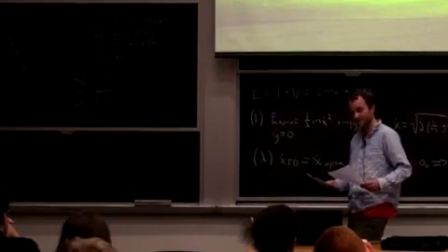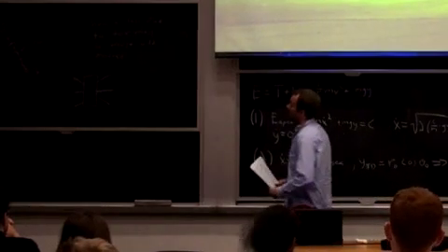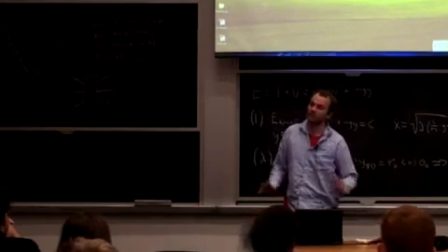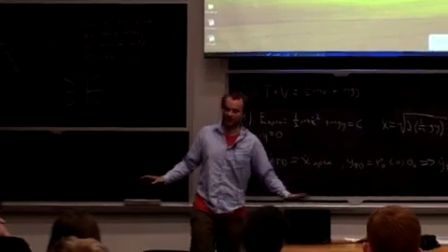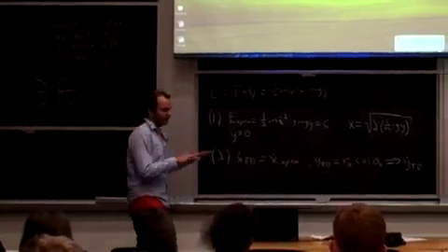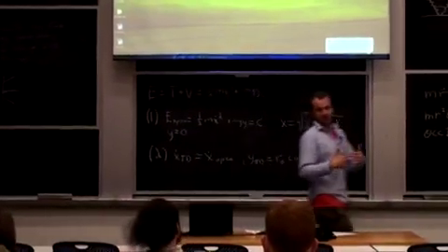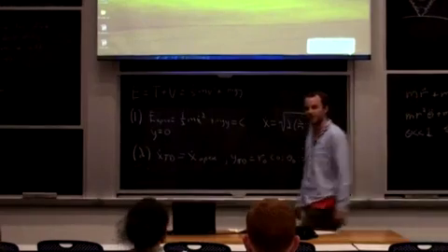In that model, is the spring actually in 3 dimensions? Is it now that you have X, Y, Z? And it's at an angle in both pitch and yaw? Yeah, I mean, if you're doing the lateral plane, I think you have to have some sort of springiness like that can push you through. But you can actually look at the cockroach running along the sagittal plane, and you don't need the 3 dimensions. You can treat several legs, I think, as one spring in the tripod.